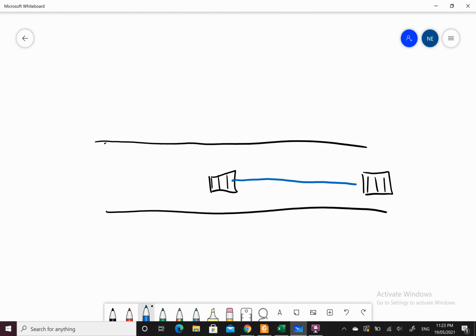If I have a pipe connecting them together, all right, I have some flow in this pipe, QU. I have some flow, QG, that's going to go into this pit. I will then have flow in this pipe here, QO, which then becomes QU. I'll have QG running into this pit. If this has 80% capture, 20% will run past and end up coming down here.